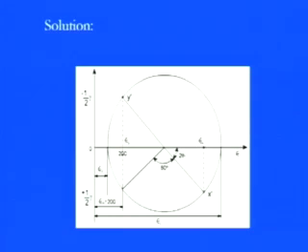Come to the solution. Now you see here, as I told you, first what we need to do, we have the x dash coordinates, we have the y dash coordinates. So you see, simply plot the epsilon and gamma here, plot those x and y on mutually perpendicular axes, plot those x dash and y dash, draw the line. Once you draw the line here, now you can make this particular circle.